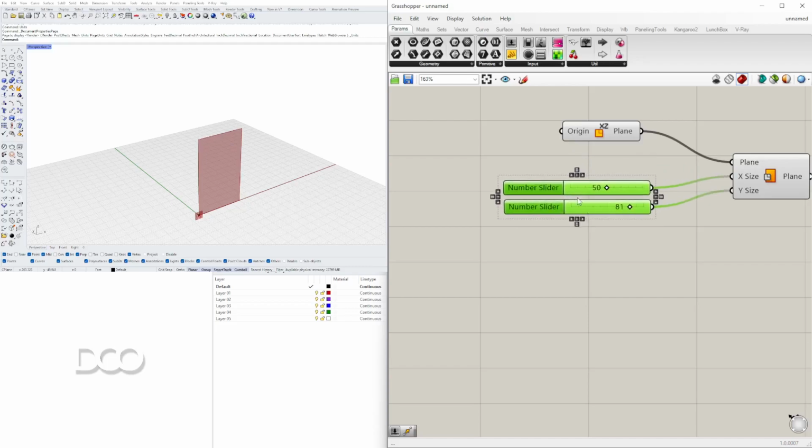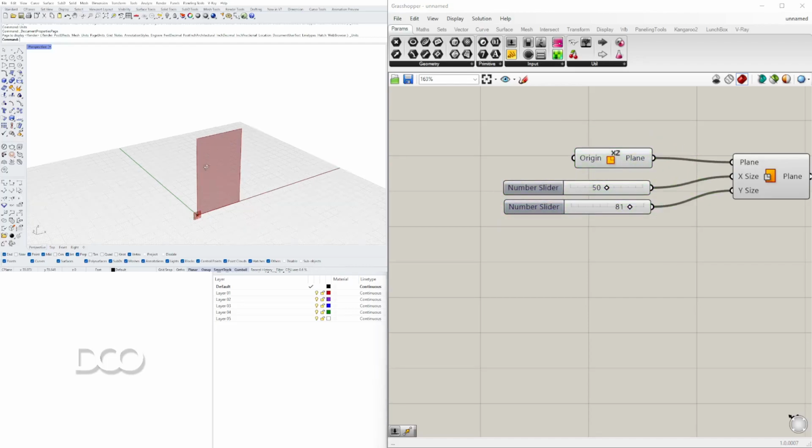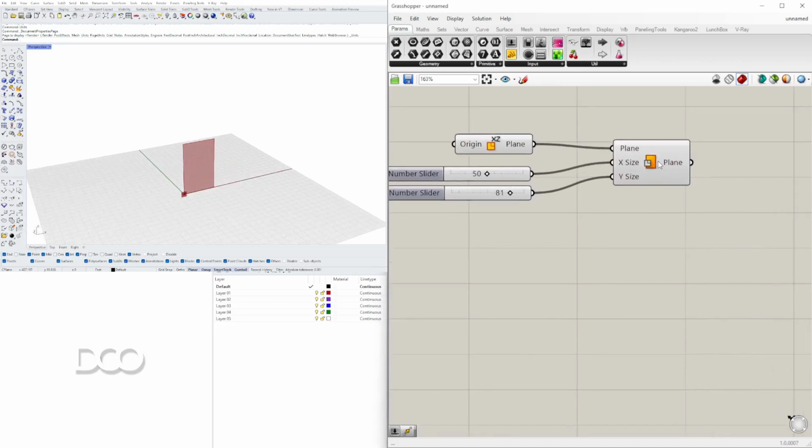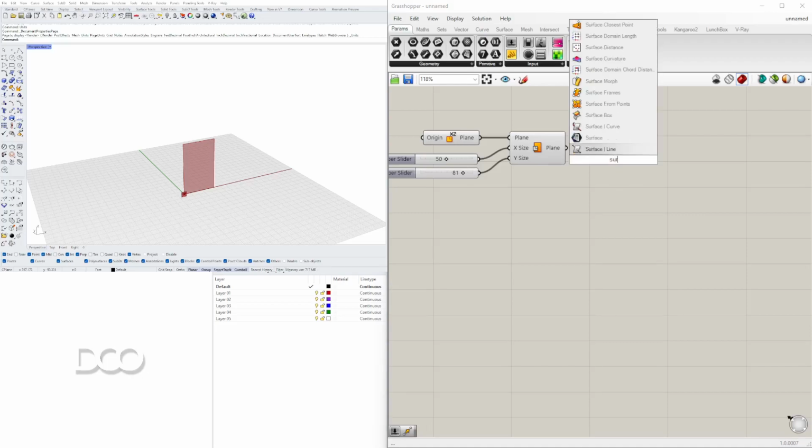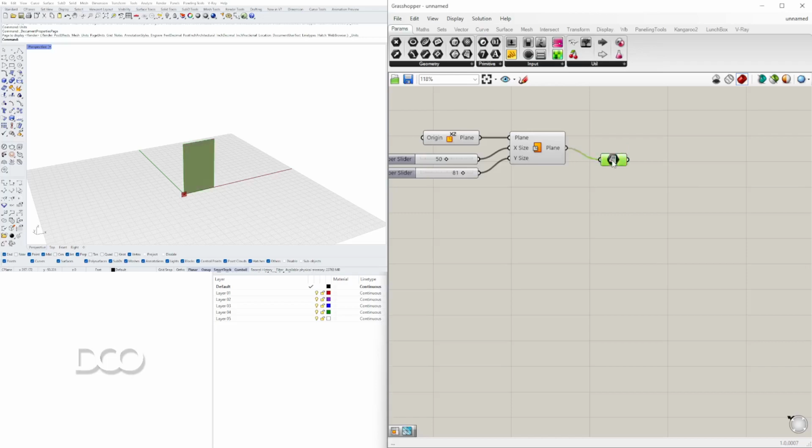What we want to do by default, I would say, is be able to change what surface we're working with. This way you don't have to create it parametrically, and you can actually insert, let's say, a different surface rather than this one that we're creating here. But the reason why we're doing it like this is to do it fully parametric here, and then have the ability to change it later. So now with this plane, we'll plug that into a surface input. This will allow us to change this input, so we can unplug this and we can set one surface to something else.